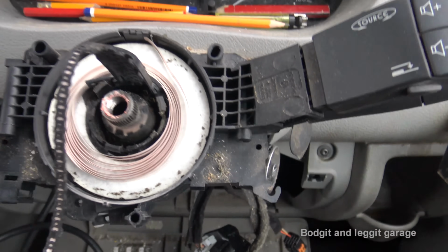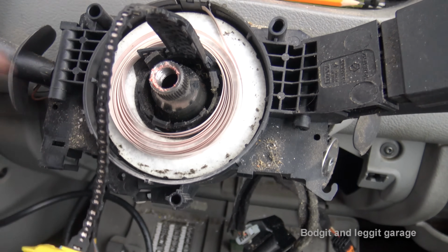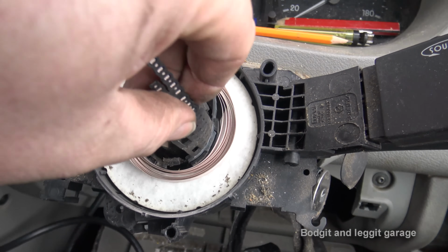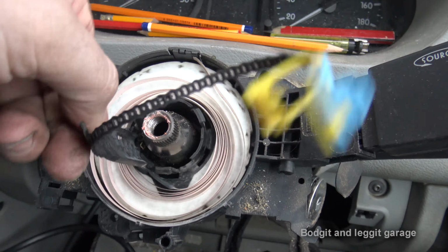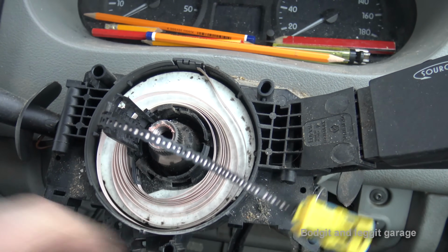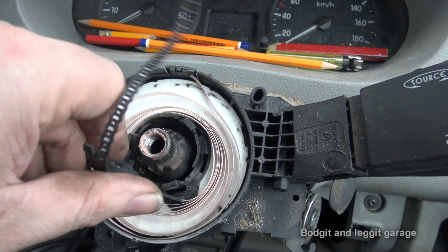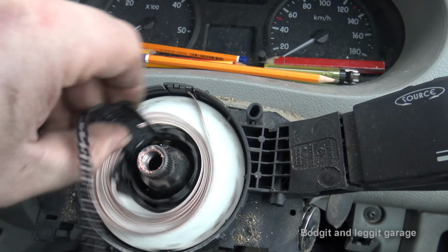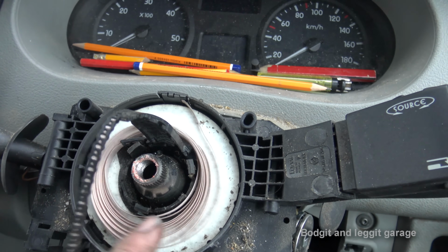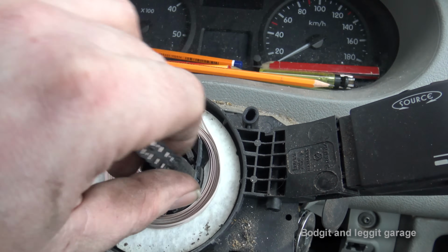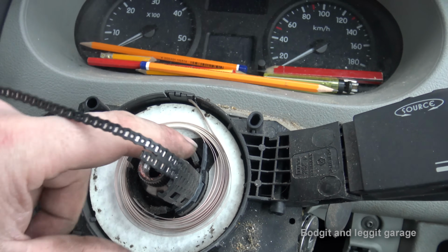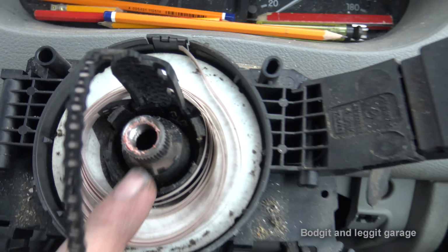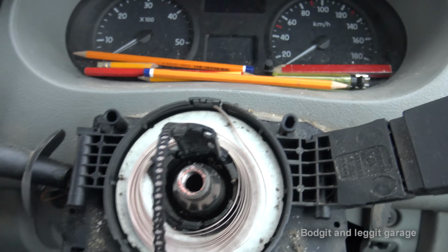Now, this is kind of inside the clock spring. This was the wire I was telling you about, and as you can see, when this moves, you can see what it does. It's constantly screwing up and moving, but that constant moving and rubbing together eventually does wear them out and cause them to do all sorts. So that's essentially what it's doing inside, and that's why it's important to get this in the middle, because if you're two ways one side and you turn your wheel, you're going to snap this. So that's essentially what happens. Inside there somewhere is the short.